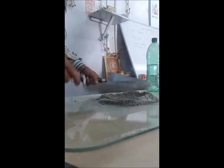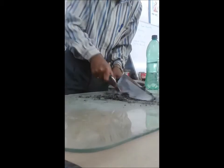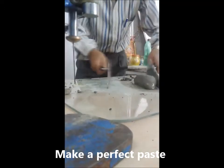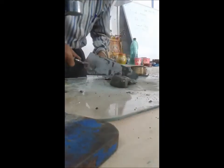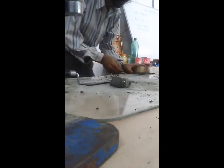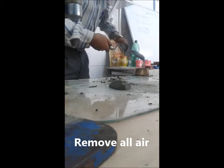102 milliliters of water as per consistency, 0.85 of 30%. Water should be mixed properly to make a perfect paste. No air bubbles should be present in this paste. Now we make the cement paste with water quickly. Then the cement paste is filled in the mold with a smooth finished surface. The mold is placed in the Vicat apparatus and the 1 mm needle should be released for penetration. Fill the mold properly with paste with a smooth surface and place it in the Vicat apparatus to check the desired penetration.